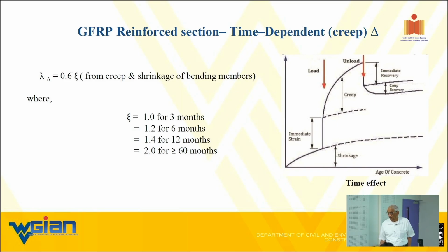What we are saying is that live load for computational purposes is only 20% from the creep deflection computation point of view.